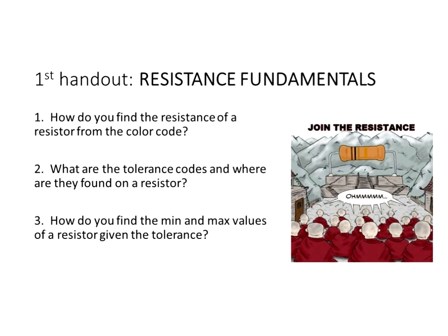Okay, your first handout should say Resistance Fundamentals on it. And there's some very, very basic stuff. This is really nice for you to review. For example, how do you find the resistance from a color code on a resistor? Well, there are 4 stripes there. The first 2 numbers of the striped colors, and you've got to know those color codes, are the first 2 numbers of the resistance.